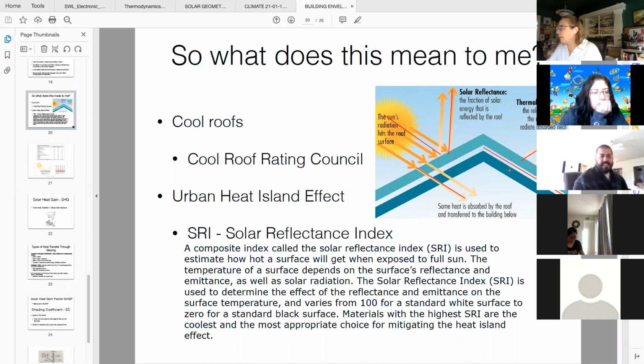And typically they're made out of some type of polymer, including a lot of aluminum in there, because it's going for a very shiny effect, that radiation is hitting that shiny metal layer and reflecting back out. The one thing that is important for a radiant barrier assembly, though, is you have to have an air gap on the interior side of it.